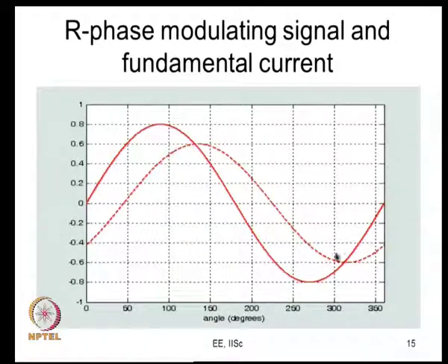So, when you have this current, the next question is what happens? There is energy loss. On this fundamental cycle of 360 degrees, you will have several switching cycles, something like one every degree, every 2 degrees or something like that. For small ratings you may have one cycle of switching. So, is there energy lost in the device on account of switching? Yes. How much energy is lost on account of switching?